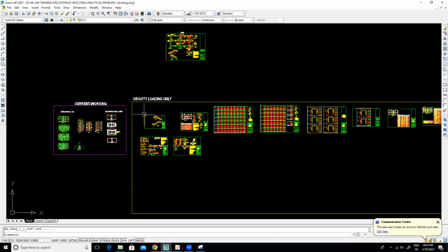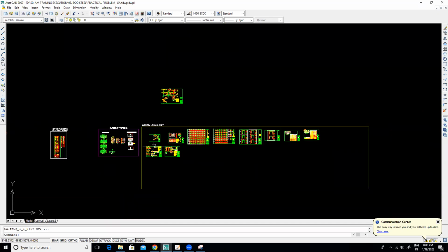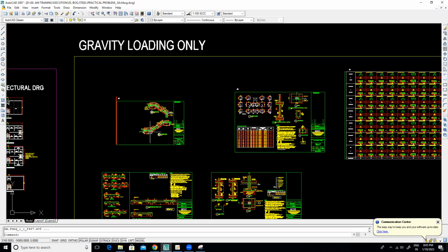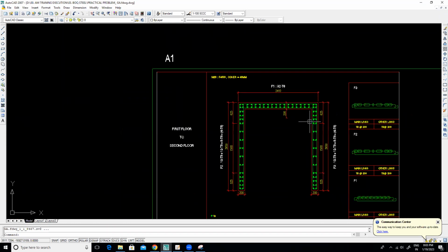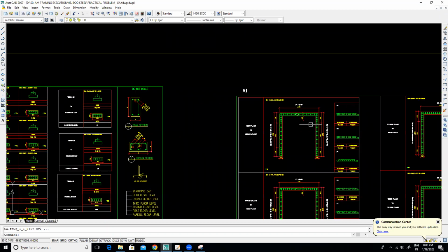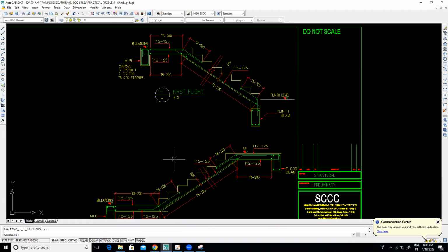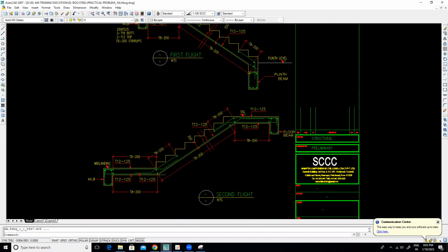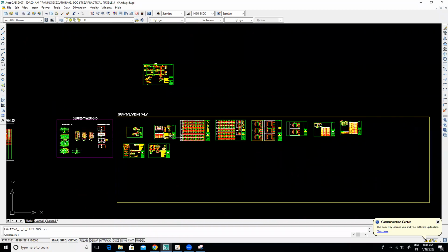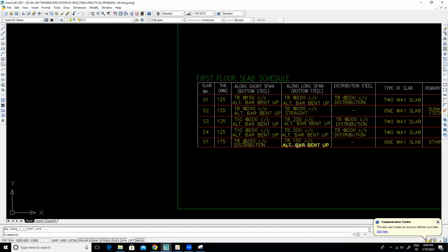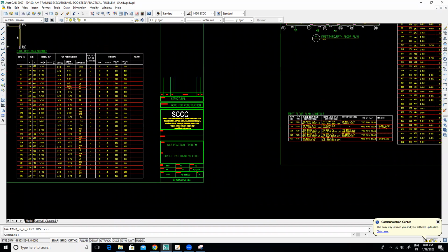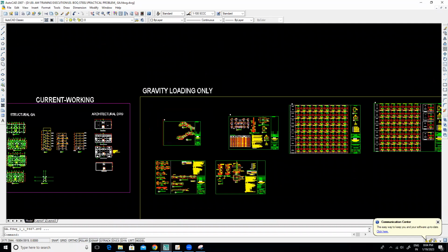बाकी क्या है इसमें. So I think this is the quantity calculation for RCC structures. And for homework, I'm giving you to do this for the shear wall calculations, stirrups and main steel, and this also, staircase. Staircase में अभी बताता हूँ मैं क्या है reinforcement. Staircase ST bar 175 thickness, distribution is 8 at 200 and main steel is T8 at 150. For the staircase. अभी staircase में